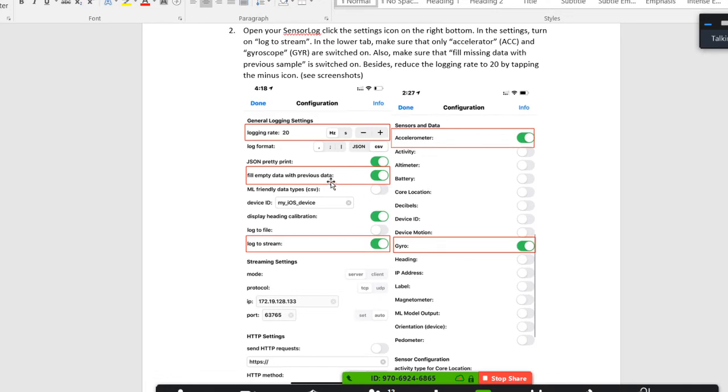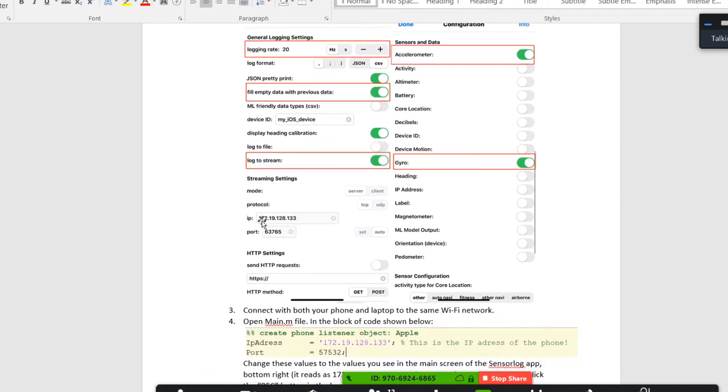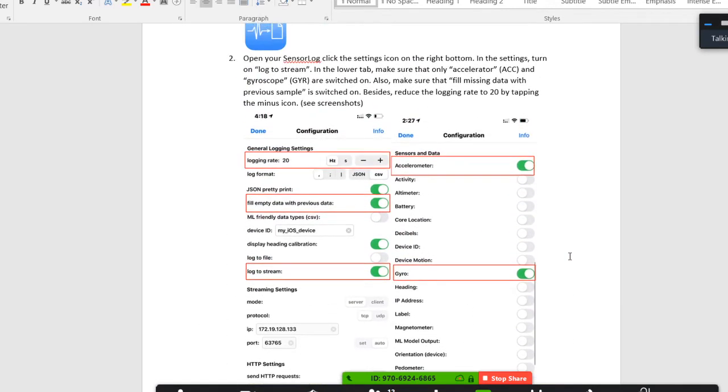I show from here. So they have lots of settings you need to set. For example, the most important thing I think is you need to set the protocol, the IP, because they use TCP/IP for communication. And the important thing is the rate, because this sampling rate is very important. If the signal changes very fast, you need to sample fast enough.